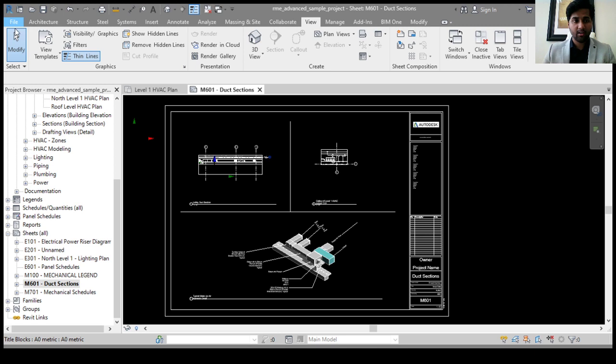If you go to File, you have the option to export this particular view into different CAD formats. You can convert to the original file, which is a DWG, or you can also convert to DXF, DGN, or any other file formats supported in CAD. You also have the option to export your Revit file into various other formats like IFC or even DWF or FBX files.